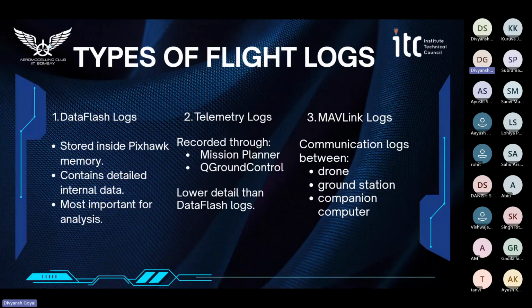So there are some types of flight log. First is the data flash log, which is the most important one. All the internal information is recorded in the data flash log. Internal information in the sense of all the IMU data inside the Pixhawk, all your internal data, and for a normal manual flight, the data flash log is the most important thing.